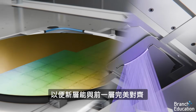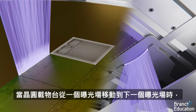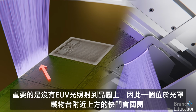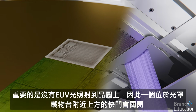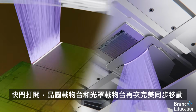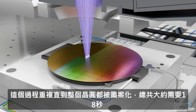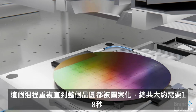with the previous layer. When the wafer stage moves from one exposure field to the next, it's important that no EUV light hits the wafer, and thus a shutter positioned up here near the reticle stage closes. Once the wafer stage is positioned to pattern the next microchip, the shutter opens and the wafer stage and reticle stage move in perfect synchrony again. This process repeats until the entire wafer is patterned, taking around 18 seconds in total.